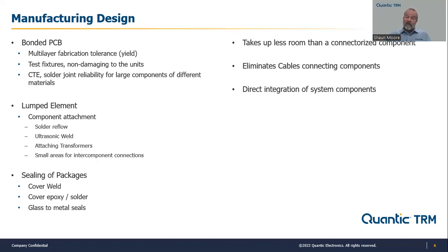Also, there is component staking as these things are moving up into the next higher assembly. Things like transformers need to be staked so that they can survive the vibration in the next environment. It's a little bit different than how we would probably stake them if we were going into a full closed housing, but the same idea needs to happen, and these components do need to be staked.